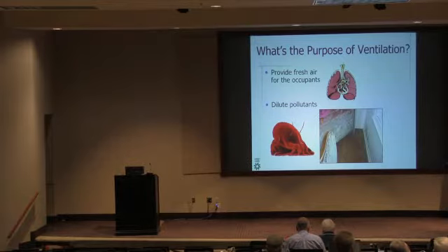They are relying on the house to ventilate, and unfortunately, you've probably all heard the house has to breathe, which is this idea that it needs air changes for indoor air quality and for drying potential and all this other stuff. And it's sort of like, well, we prefer that we not get our house wet to begin with, which would be one thing. And then really, the air changes that we want are for dilution of pollutants, which could include moisture, and for indoor air quality and human comfort.